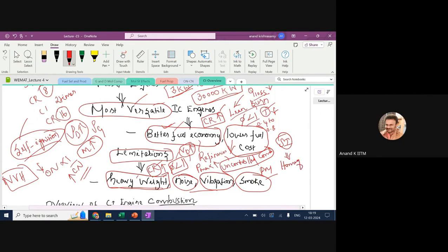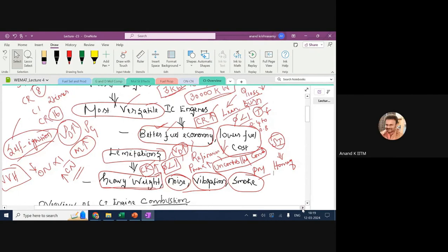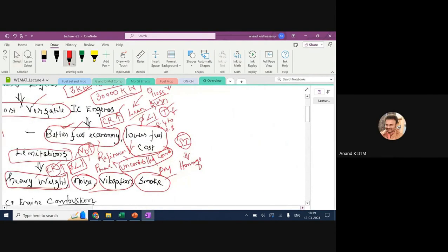So you have homogeneous mixture combustion in an SI engine. You have a homogeneous fuel-air mixture. That's what we discussed earlier in SI engine combustion. You have an external mixture preparation based combustion mode. You provide longer time for mixing fuel and air because you inject or introduce fuel during the intake stroke, and ignition starts at the end of the compression stroke. You provide longer time for fuel-air mixing, and the fuel is highly volatile and can readily vaporize. All this leads to better mixture preparation, and you end up forming a homogeneous mixture.